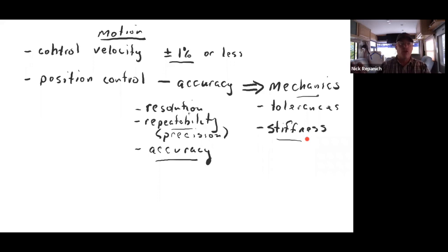Some can be really strong and hold a lot of weight, yet be compliant. Titanium. You think of titanium as this great metal, but it's actually rather springy. You don't see tandem bicycles made out of titanium, because by the time you get out there, they're noodles. But boy, that strength curve just keeps going and going linearly. The strength to weight ratio is great, but the stiffness is terrible. So anyway, it's a thing.